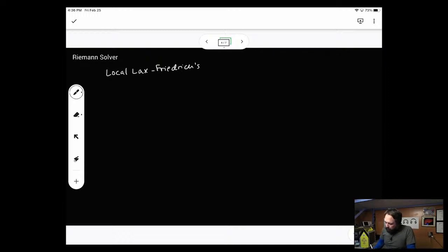And again, the problem here is, so here's my element boundary. I've got a bunch of nodal points where I have estimates of the solution from either side. So I have what I'll call the solution on the left. I have the solution on the right. And the normal vector is going to point from the left state to the right state in this setup. And so in the code, the way this works in SELF is you're always thinking about where you're at in the context of this primary element on the left side. And we can compute what those exchanges need to be. So here I've got n hat. I think I've got everything specified I need to.